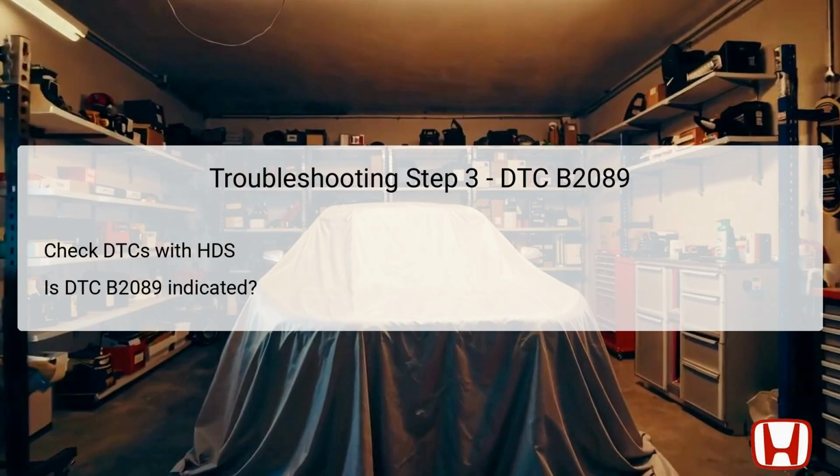After activating the power sliding door switch, the next troubleshooting action is to check for any DTCs using the HDS. This diagnostic tool enables technicians to evaluate whether the DTC B2089 is still indicated after the switch has been operated as described.